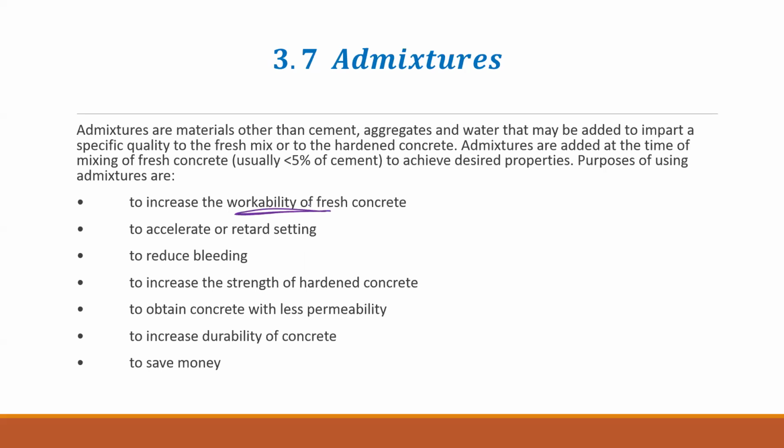We can have plasticizers and superplasticizers to control the workability. Sometimes when we do the concrete mix design, we have to control the amount of water added to a concrete mix, because if we add more water, that will affect the strength. But when you have less water, it is hard to do the mixing. So we need something to improve the workability without adding water.